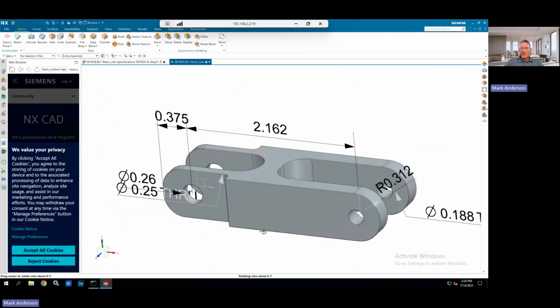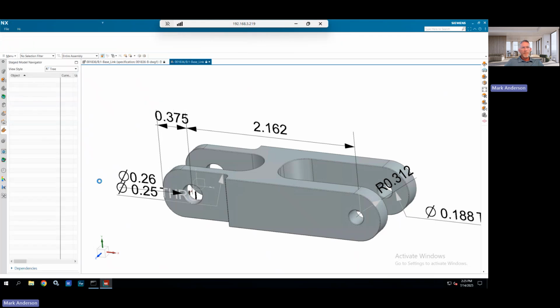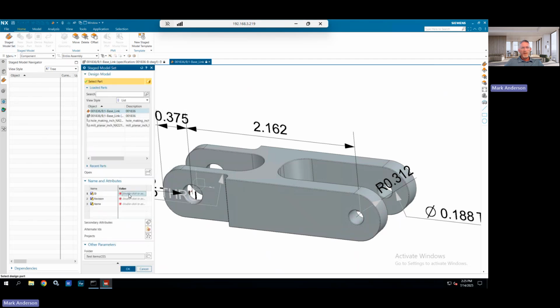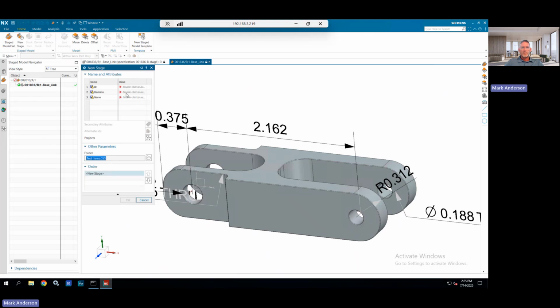So in your CAM file, you're going to have to manually tell it to stop and do these things. It's manual interaction and interdiction from the user to get what you actually need. The easiest way to go about this is to physically create everything all at once in a project stage model type of operation. How do we do that? First thing we do is go Application, this More tab, Stage Model. It's taking this original, and then we say there's going to be one more. We give an identifier. I'm using the automatic one just so it's simple.